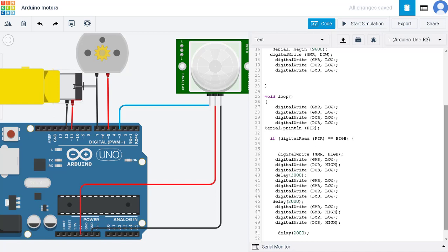That's why here I am going to open a new bracket, and the process that is going to happen as soon as my PIR detects a movement, first I am going to ask her to print on the serial monitor a message related to the thing that is going to happen as soon as the PIR detects a motion. So in this case, I am going to type open door because that is going to be the message.